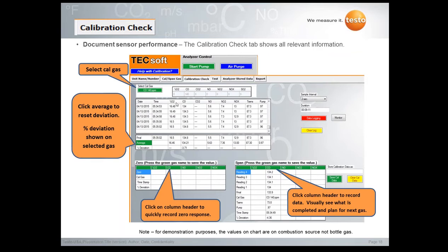I'm running now, I click over here and go to an air purge. I'm using a purge to go into the analyzer to zero the analyzer out. And then I would click these buttons right here. Or if I'm using nitrogen. But I can do a quick zero just by running the gas. The gas would fill in and you'd see this log data and just go click, click, click, and click, and I've just done all these zeros.